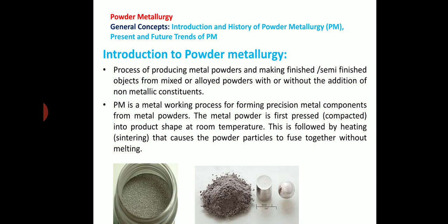Powder metallurgy is a highly developed method of manufacturing, reliable for ferrous and non-ferrous parts. It is made by mixing elemental or alloy powders and compacting the mixture in a die. The resultant shapes are then sintered, or heated, in a controlled atmosphere furnace to bond the particles metallurgically.